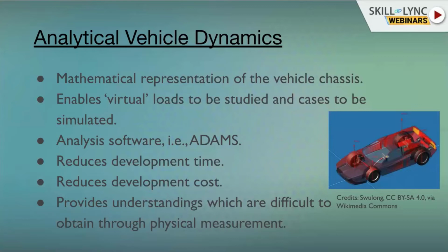It also provides understandings which are difficult to obtain through physical measurements. So certain parameters, for example, dynamic camber gain, toe compliance, they're very much parameters that are difficult to measure physically. So using the advantage of mathematical models, you can provide very quick and accurate assessments of those.